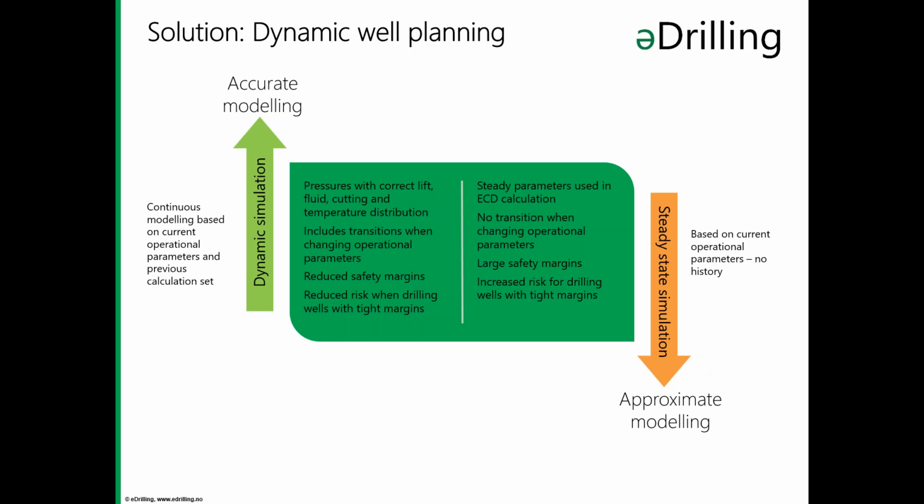So what happens when you have a model with steady-state simulations? In this case, the parameters used in the ECD calculation are unchanged, and also transitions are not taken into account when you have operational parameter changes. So the safety margins are wide, the risk for drilling wells with tight margins is increased, and therefore the model is not accurate.